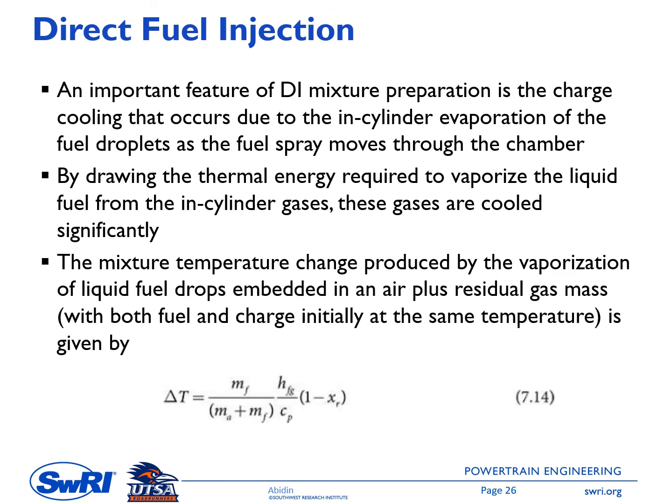In this case, we assume that the fuel spray evaporation is 100% from the air mixture. And then by drawing the thermal energy required to vaporize the liquid fuel from the in-cylinder gases, these gases are cooled significantly.